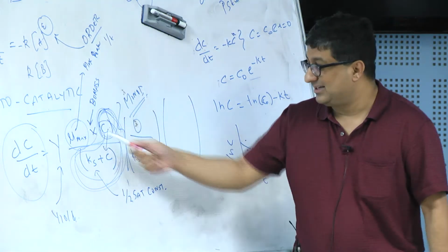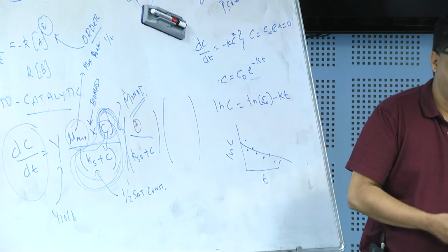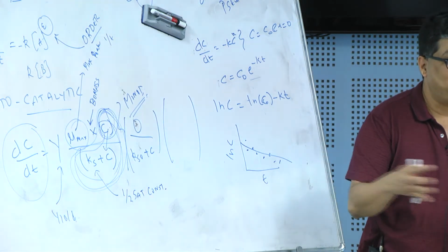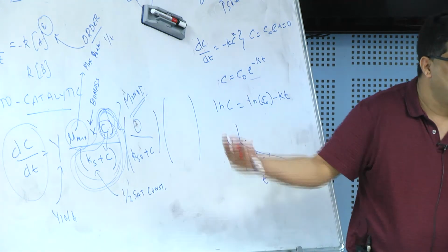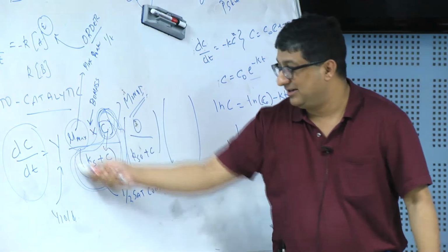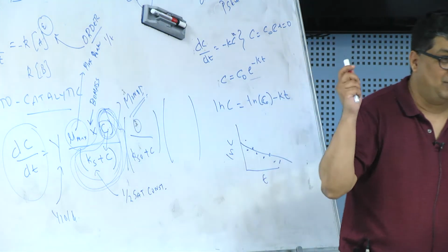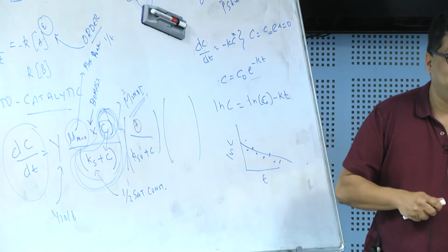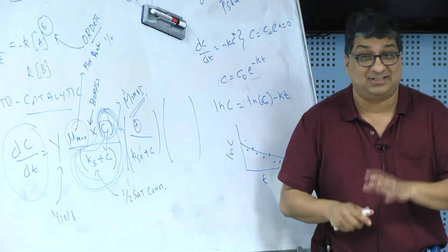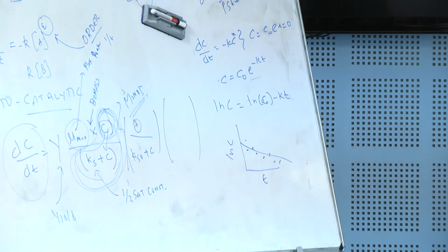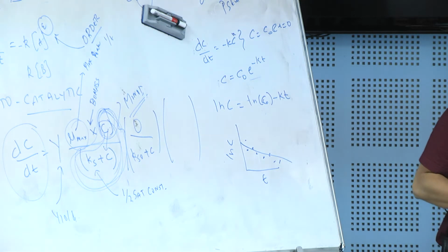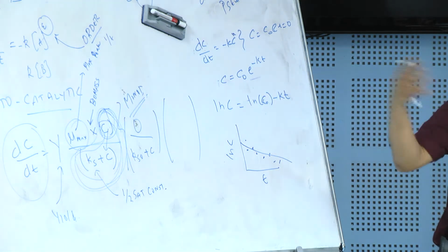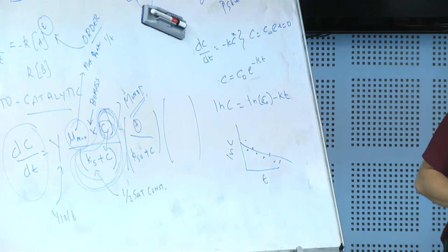Okay, technically that biomass rate changes over time, but since we are looking at steady state and wastewater treatment in our activated sludge design, we just put a constant and get rid of it. We say we'll put 1, get rid of it, and the rest of the numbers will change to account for that. Okay, but that assumption is never written in any book, and a lot of people don't even know. If you ask them how to write Monod kinetics, they'll not even put the x. But that's not Monod. You need to have the biomass or something, because the reaction goes from something to something, and that needs to be captured.